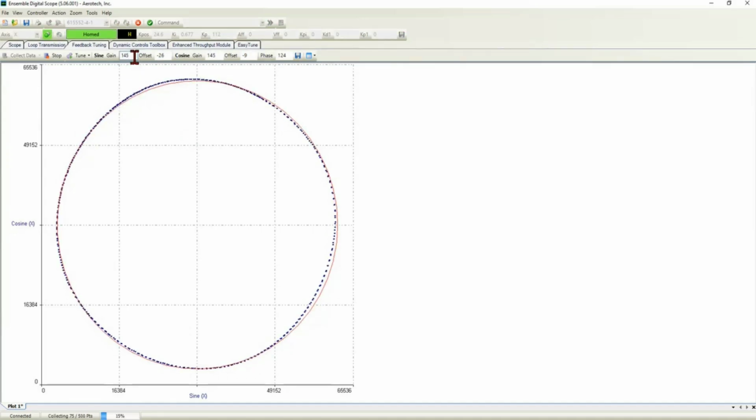When you look at the Lissajous pattern, you can also tell something about it. If the gain is not near the circle and not equal to 1, as long as it's greater than a half, it's usually enough signal. But you can also see if maybe the channels are lopsided.